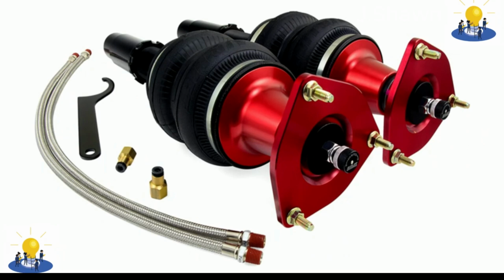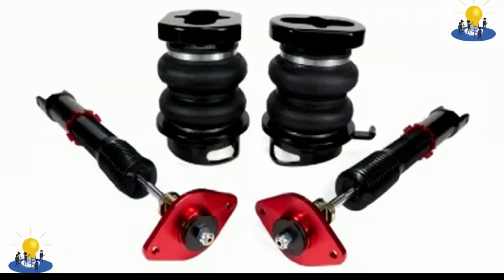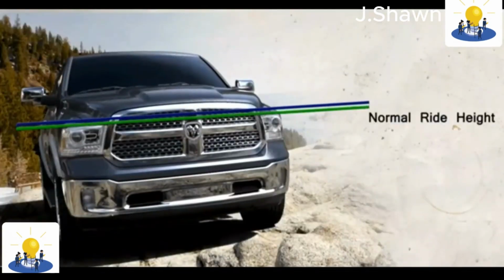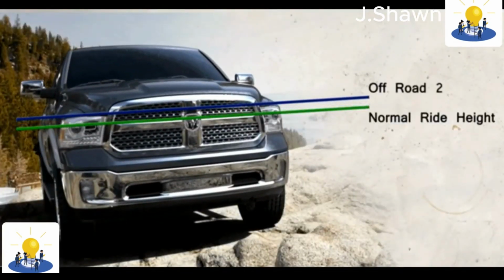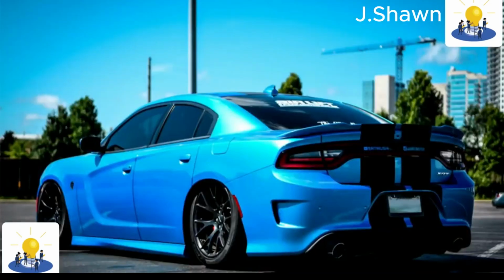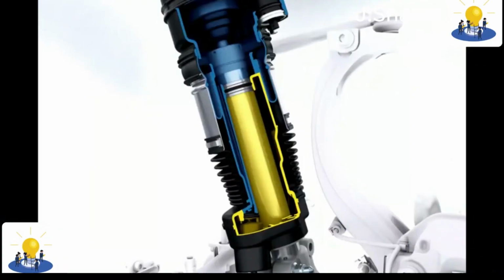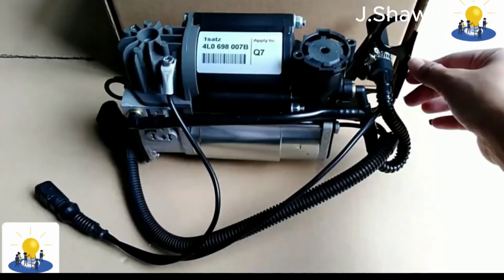When a pressure reservoir is present, the flow of air or gas is commonly controlled with pneumatic solenoid valves. This allows the user to make adjustments by simply pressing a momentary contact electric button or switch. The installation and configuration of these systems varies for different makes and models, but the underlying principle remains the same. The metal spring, coil, or leaf is removed, and an airbag, also referred to as an air spring, is inserted or fabricated to fit in the place of the factory spring. When air pressure is supplied to the airbag, the suspension can be adjusted either up or down, lifted or lowered.